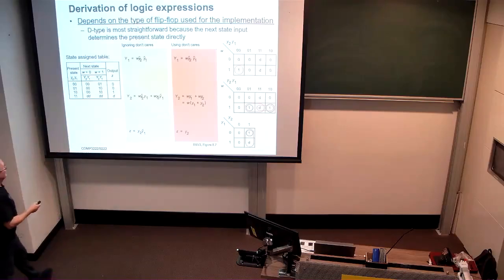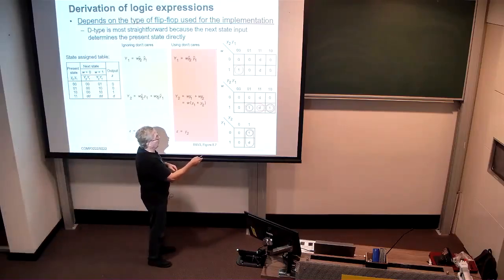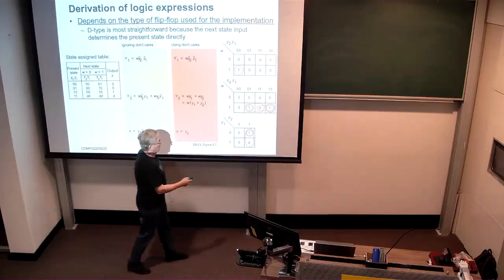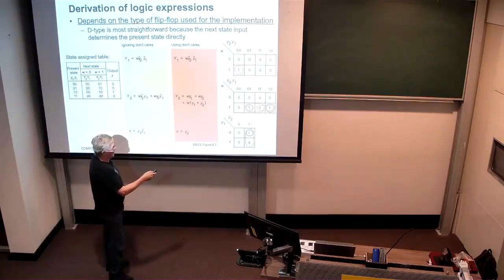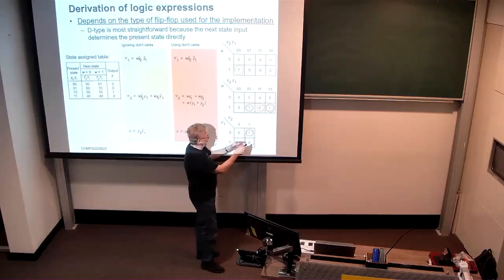However, for Y2, we can combine both of the ones that we saw previously, the exclusive OR columns, with the D that sits between them, thereby simplifying. So we can see that this is W and, well, Y1 is 1 in both of these cells, and in both of these cells, Y2 is 1.